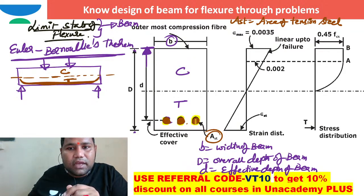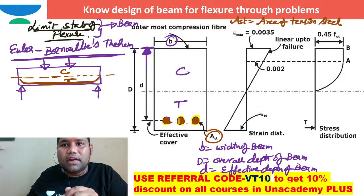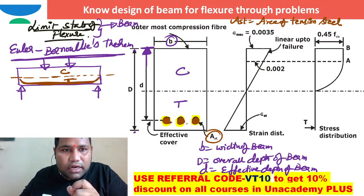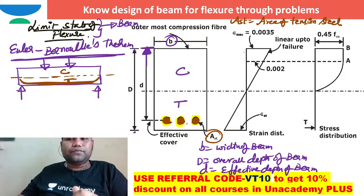The area of tension steel here we can write as 3 times pi by 4 times the diameter squared, since the cross-sectional area of each bar is pi by 4 times diameter squared. So for this example, the area of steel is 3 into pi by 4 into d squared.